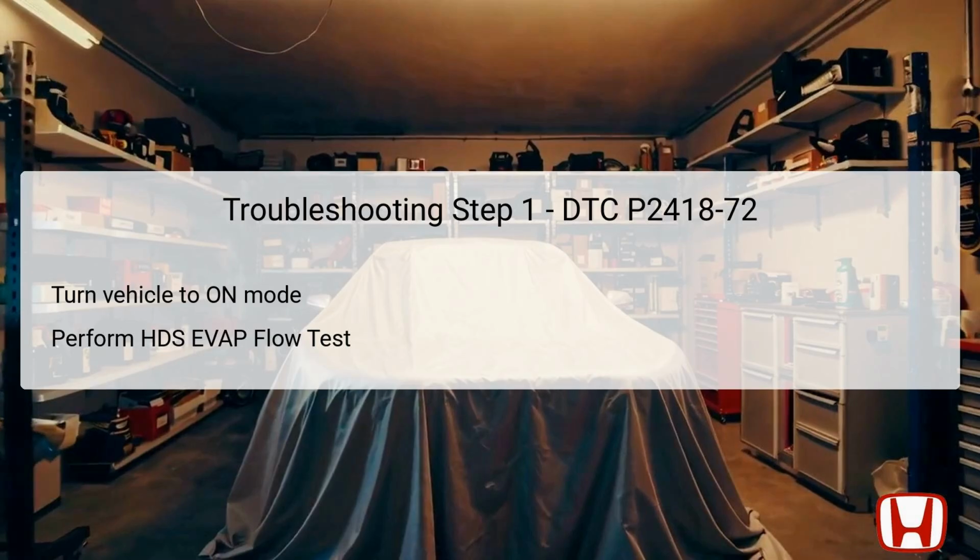This test evaluates whether the purge valve is functioning as expected by measuring the flow of vapor through the EVAP system under controlled conditions. If the result of this test is not okay, it indicates that the malfunction is likely present, therefore confirming the existence of the fault and guiding the next steps in the repair process.